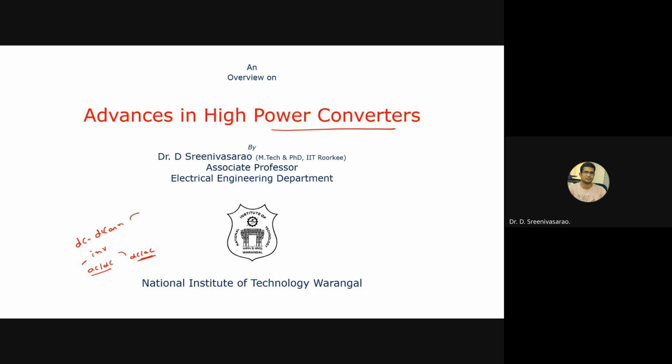First we'll focus on the power converters, especially the inverter portion. Later on we will move to the DC-DC converters. Okay. Depending on the power available, meaning how much power you require or how much power you're generating, and the voltage levels, we have several options for the inverters. Conventionally, if it's single phase, we prefer the single phase H bridge inverter or the half bridge inverter; that is sufficient if it is a small rating of PV or something, or maybe some 230 volts if you want to integrate to the single phase grid. In that case, that is sufficient.